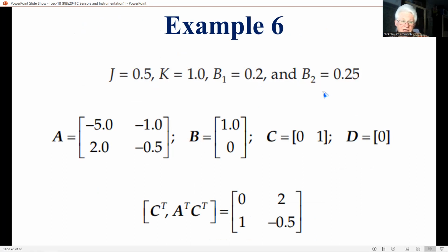As earlier, the input is omega capital, which is the diesel engine speed, and the state variables are T capital, which is the torque in the flexible shaft, and omega small, which is the pump speed. Take the pump speed as the system output. Then the matrices defining the system are, as you may see, expressions for A, B, C, and D.